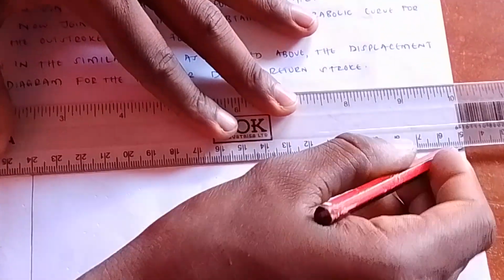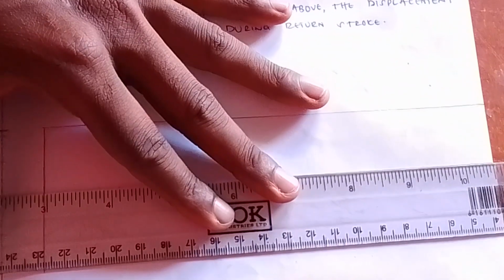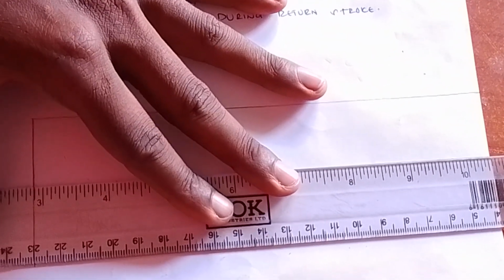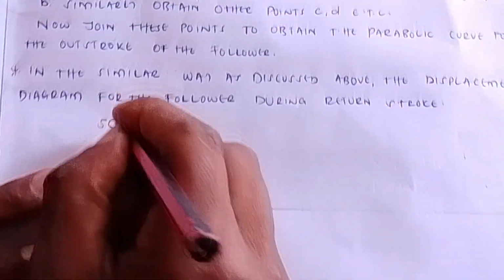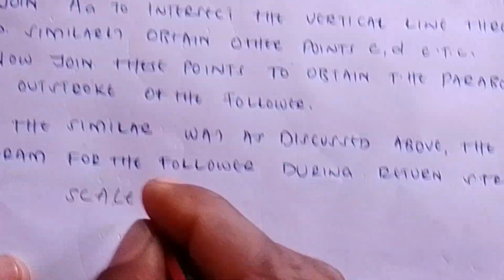Like that. Draw a vertical line with a construction line, because you must also look for a suitable scale for your y-axis, like that. That is a stroke. Then from this point to the rest of the points, we know it is 360 degrees. So we must also look for a suitable scale, and as I've told you, I myself use 360 degrees equals 18 centimeters. That is the scale that I used in my exam during my study.